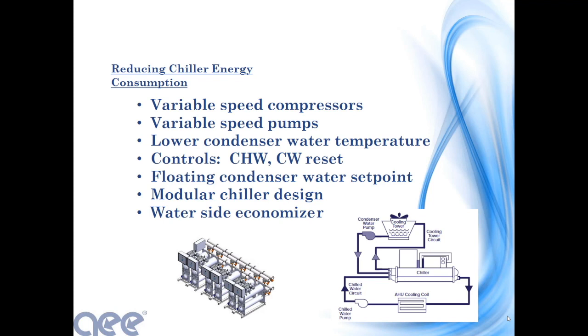And then as the load increases, gradually increase both together, so that you're climbing up that curve and you're staying on the low end as long as possible. So this can be done with 3, 4, 5, 6 chillers, whatever it takes to keep the chillers operating as close to 50% load as possible. It can save a ton of energy. It's just a control strategy, so it really doesn't require any additional capital cost.